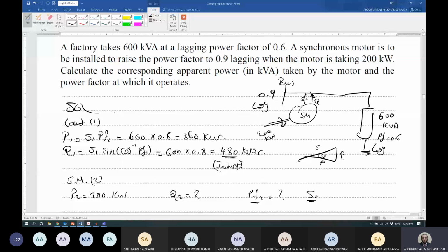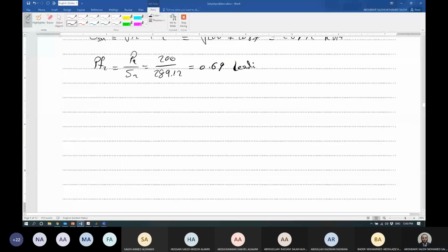Doctor, we said in synchronous machines, if used in this case, in the data class, that the power input should be zero. No, it's not a condition. Again, what we said exactly in our class: if you have a synchronous motor on the shelf and it's not used anymore in your factory, you can use it at no load to operate completely as a synchronous condenser. However, if the motor is already working and driving certain power, should you disconnect the power to improve the power factor? It's not logical.